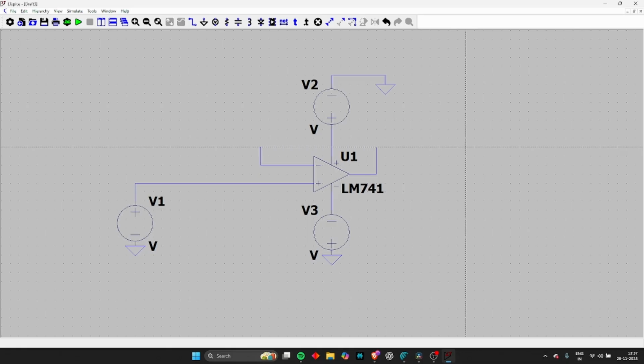The op-amp basically says, copy that. So the gain of the circuit is 1, output is equal to input. No amplification, just loyalty. But the magic is high input impedance, it won't load your previous stage, and low output impedance, it can drive the next stage easily. So in short, it acts as a buffer, like a soldier holding the line, so that the rest of the circuit doesn't collapse.